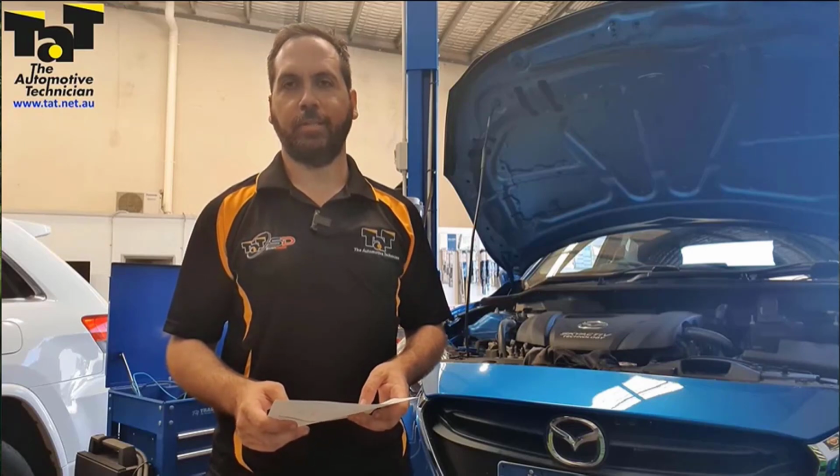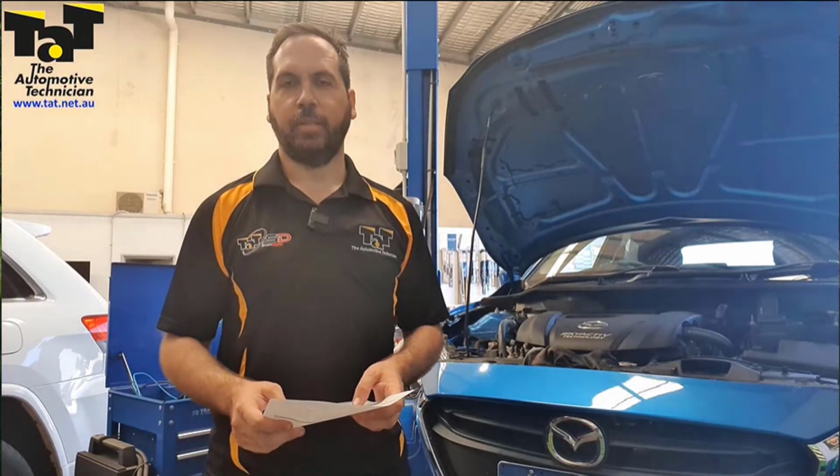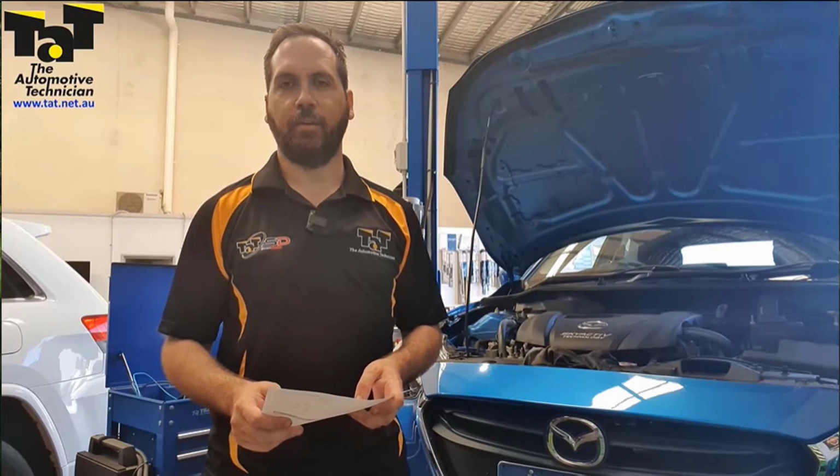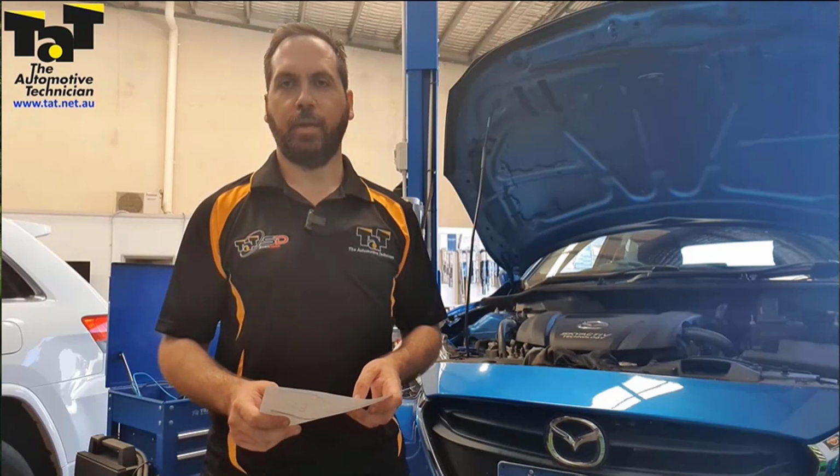So there we go, guys, a very simple and quick one today, but it just shows the importance of making sure that we're checking connectors and wiring before we start replacing components. Like I said before, the last thing we want to do is ring the customer up when we get an ABS light on, automatically assume that the sensor's faulty, sell them a wheel speed sensor, fit it, and it doesn't fix the problem. So it pays to do our due diligence and make sure we 100% rectify the fault.